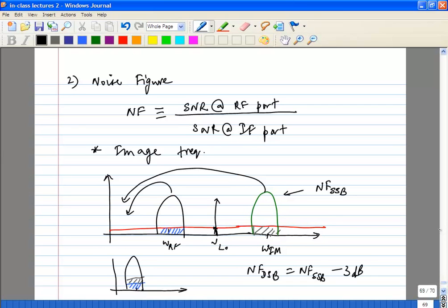What that means is, and it's broadband white noise, totally uncorrelated between frequencies, so it will become 3 dB worse. So the noise floor gets 3 dB worse, whereas the signal just comes through directly. So automatically your SNR at the output is going to be worse because your noise floor is no longer the same as at the input. Is that clear to everyone?